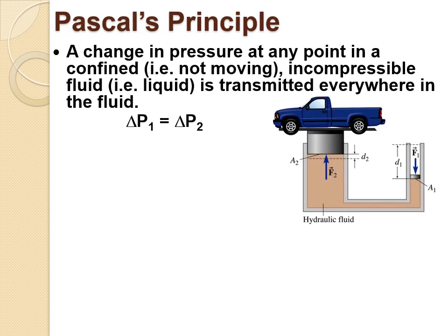So the next thing we talk about is Pascal's principle. Basically, this example here is referred to as the basics of hydraulics. So we have a small surface area over here that a force is being applied. How does that translate over here? Because the liquid itself, or the fluid, is not compressible, that means the change in pressure on this side will translate through the entire fluid and cause a change in pressure on that side.